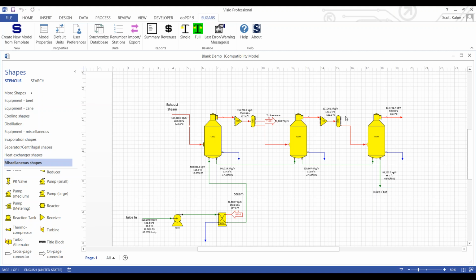So very useful thing to be able to do in sugars, because almost every sugar factory is set up that way, and it's important to get the correct vapor headers connected to the vapor users so that the evaporator balance is correct. The other thing you'll notice is that the dissolved solids content changed slightly in the intermediate effects between 1 and 2 and between 2 and 3.